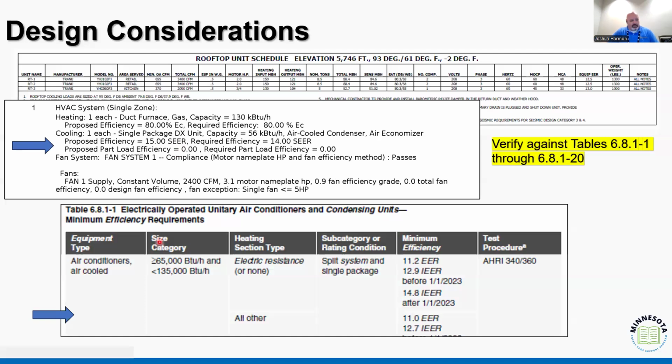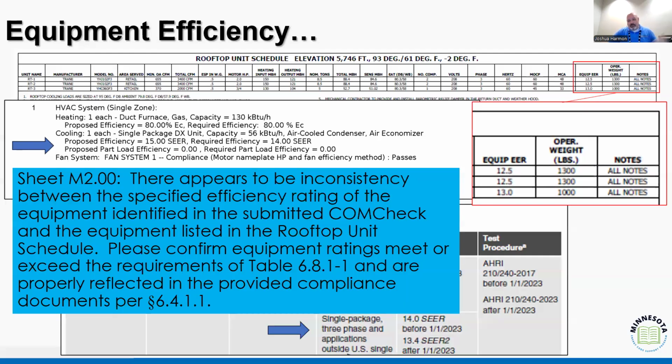So I usually ask for clarification. I'm not going to sit there and do that math. I'll be honest with you. I send a note back to the designer saying, hey, I need you to identify this in the appropriate unit of measure. I want SEER2. I want SEER numbers. I don't want these other values that you're providing me, right? And so again, I'm going to say, hey, I need these corrected to make sure they reflect the appropriate unit of measure.